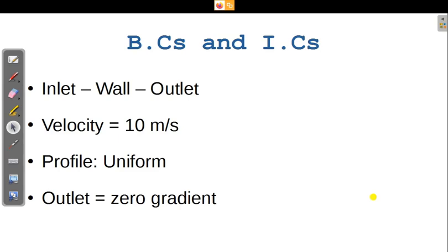It has a mathematical background where V is defined as 0 meter per second. So if I am talking about a boundary condition like the wall boundary condition, it is V equals 0. There are other boundary conditions like outlet. I have given an example called the zero gradient boundary condition. The zero gradient boundary condition is typically when you have a boundary surface wherein the internal side and external side have the same value. For example, pressure is 100 Pascal on the internal surface and also 100 Pascal on the external surface, so 100 minus 100 is 0. That's where you have zero gradient. So that's how it is defined.